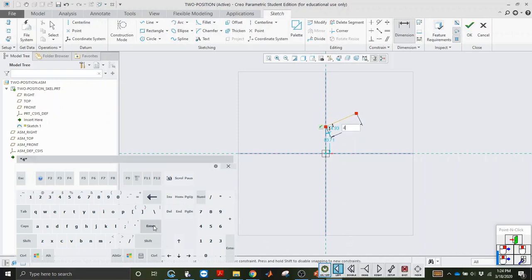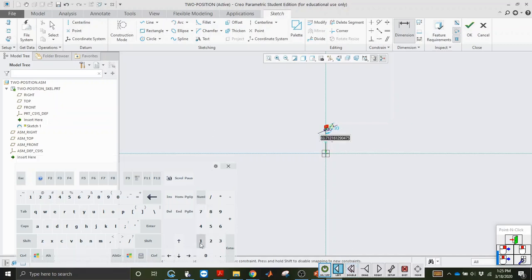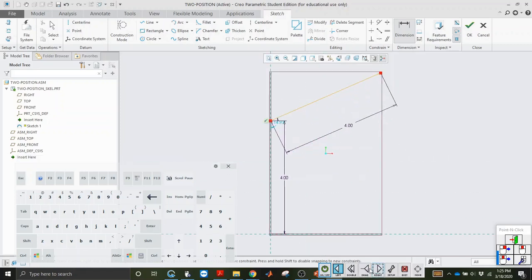So we're going to make this coupler 4 inches long because it's a small part. It doesn't have to be 83 inches from the origin, so let's just say 4 inches from the origin. And then we can zoom to fit. And then this angle is right now referencing the vertical axis or vertical plane, but I tend to like to have it reference the horizontal plane so you can know exactly how off the horizontal it is. So let's quickly get this dimension against these 2 planes. Click Control too many times. Boom. And it's at 24.93, but I'm OCD, so let's do an even 25.